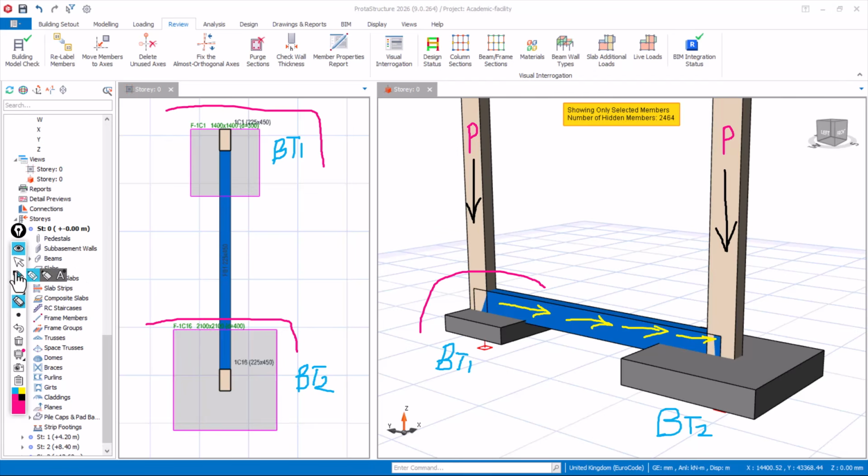It is not going to rest directly on or have any contact with the soil, as you can see here that it is being lifted off from the soil. So the only thing that will have direct contact with the soil is just the footings. Only the footings are going to have direct contact with the soil, and the soil contact on this eccentric footing area must not be triangular, it must be uniform. Else, if it is triangular, it's going to cause an overturning around that place on that footing.